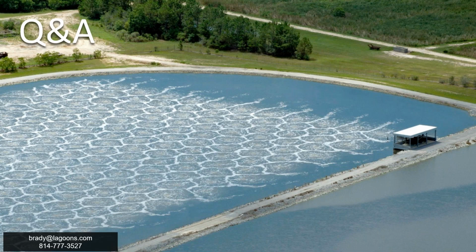in general, for 99% of lagoon systems that we see for fine bubble aeration, blowers are the way to go. Unless you're looking at a backyard pond that's not wastewater and you just need a couple of SCFM, a compressor is a good way to do it. Compressors can get significantly higher pressure, but it's rare that we see lagoon systems deeper than 20 feet, which might be a 10 to 12 PSI system. Blowers can do 12 PSI all day long. If you're getting up towards 30, 40, 50 PSI, I don't know where you're pumping air, but a compressor might be better suited for that application.